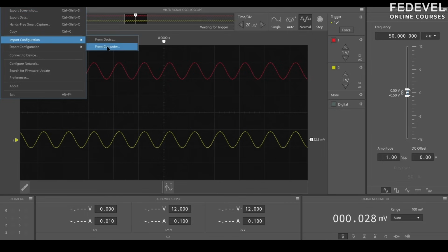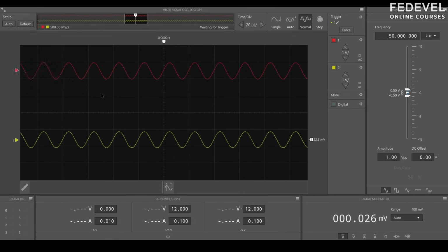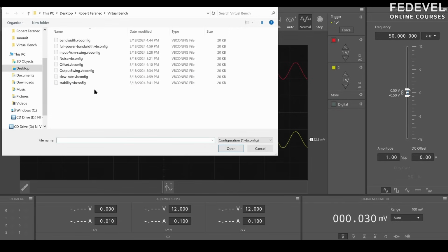So you would expect it would have really good noise performance, but in reality, its current noise, which is really the bias current noise of the device, is not as good as the OPA188, the DC optimized device.